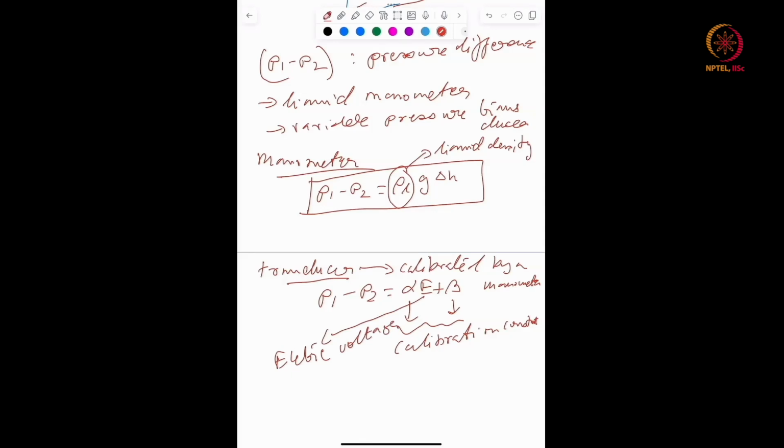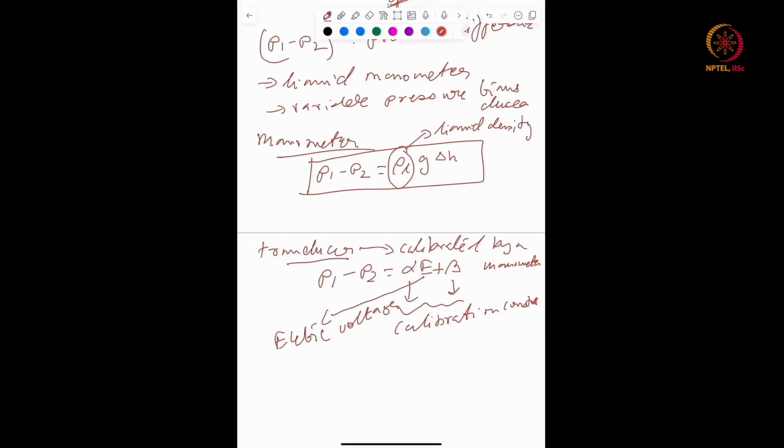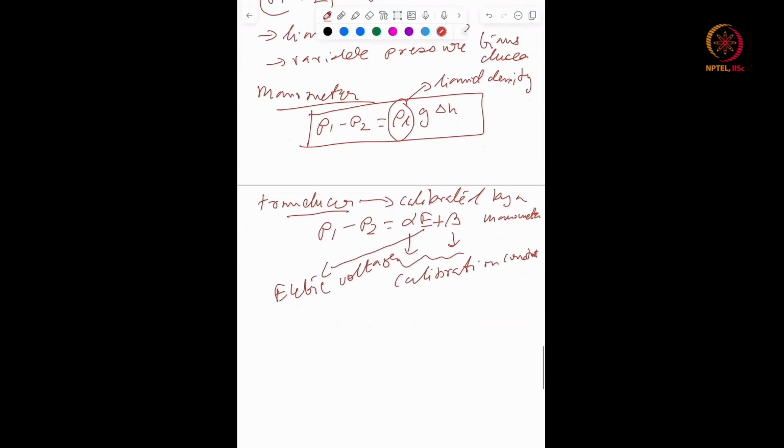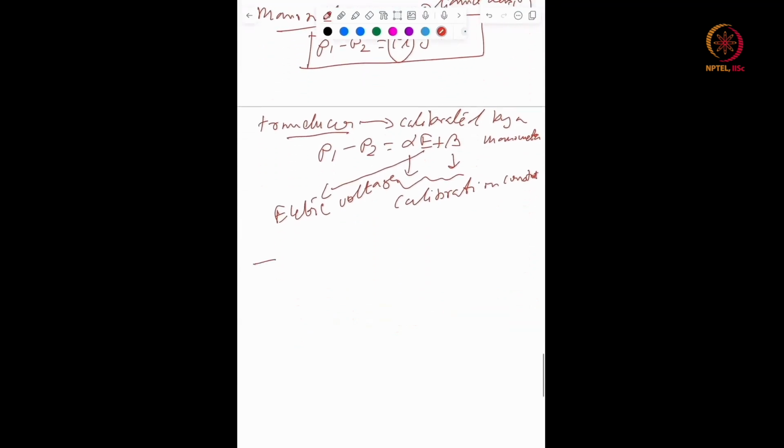So this also measures by a strain gauge. There is a strain gauge in between which gets deflected and which leads to that. So the static sensitivity is the slope of the input output relationship. If you put it like this, static sensitivity is basically the slope. So if you have an input output, this is the slope. These curves can be anything.